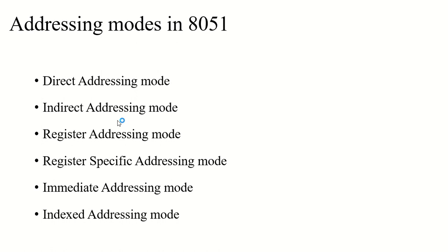In this instruction opcode, 3 bits are reserved for specifying one of the registers from the selected register bank. And for selecting the register bank, the user has to modify 2 bits in the PSW.